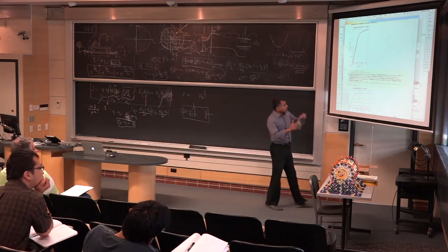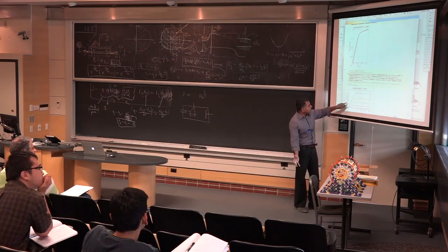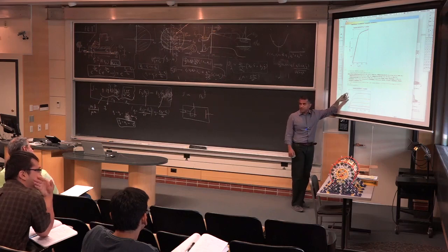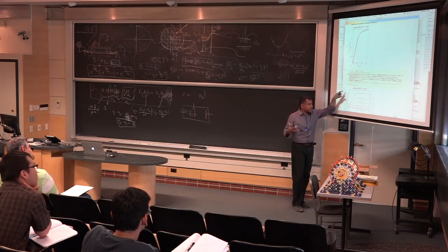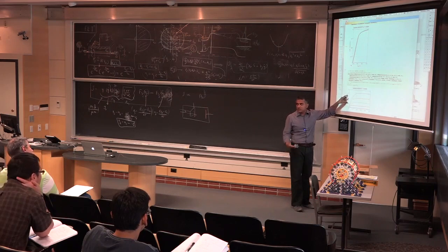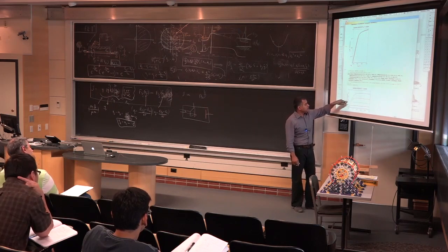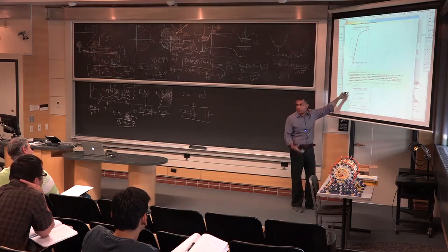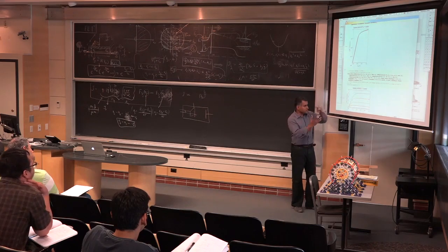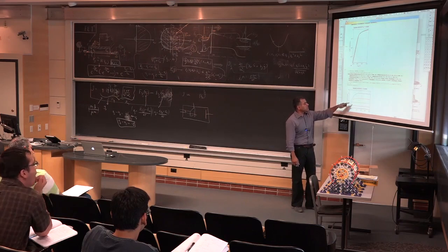So look at the numbers. Numbers of the order of 1 milliamp per micron. And that's today's MOSFETs. The best transistors today are around there. 1 milliamp per micron, 2 depends. I mean, for example, in gallium nitride, people have reached almost 4 milliamp per micron. This is with very short gate lengths and that sort of thing.